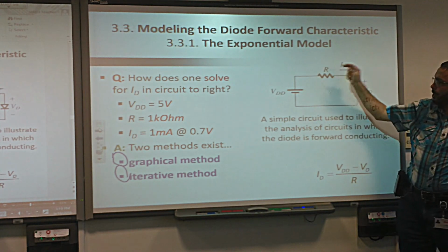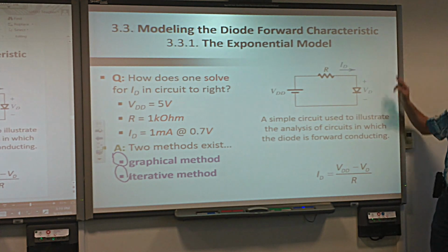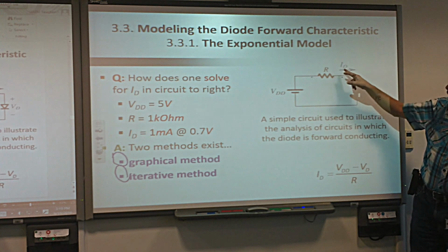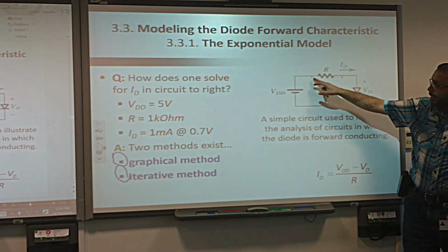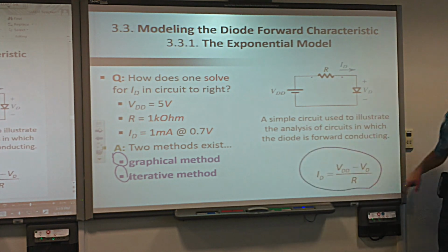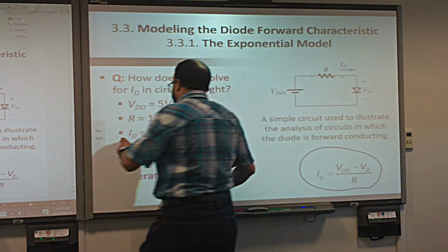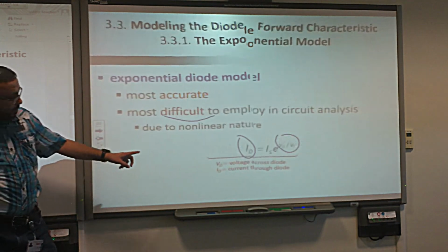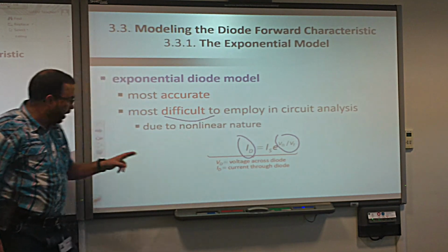Now, the equation for the resistor is I equals this voltage minus this voltage, because we have taken the current going this way, divided by R. This is the IV characteristic of the resistor, and the previous one is the IV characteristic of the diode.